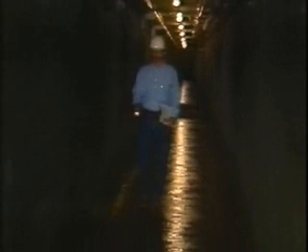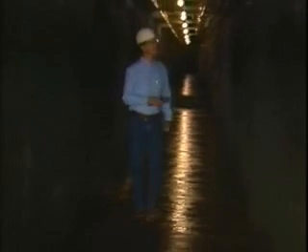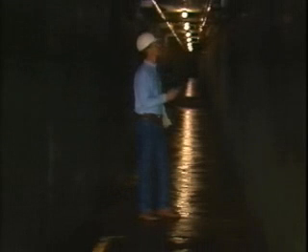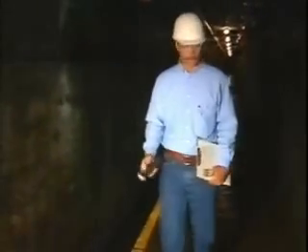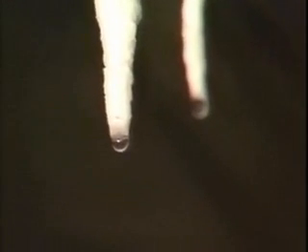Now let's turn our attention to inspecting the interior of the dam. Concrete dams usually have galleries inside the dam. The galleries allow for the inspection of the interior and provide access to foundation drains, operating equipment, and instrumentation. These galleries should be well ventilated and well lit to ensure safe and adequate inspection. Many deficiencies found at other places in the dam will also be found in the interior. These include cracks, concrete deterioration, surface defects, and leakage.